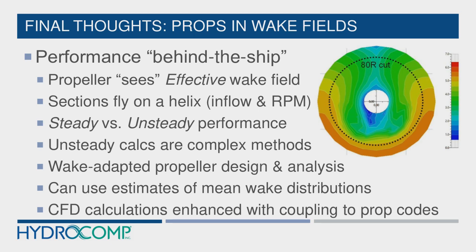What we're proposing is, if we can get a decent estimate of an effective wake field distribution, and we go to system level calculations like NavCAD for the prediction of effective wake fraction, we can scale just a little bit what our estimates are. And so that's how we would do that in the absence of CFD here.